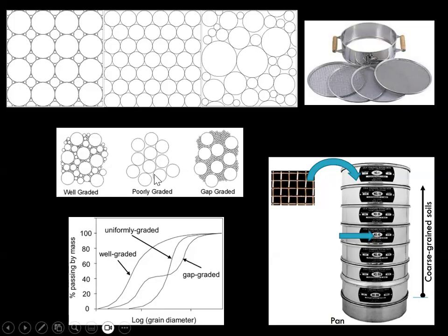But what do you think is the strong part and what is the weak part of the concrete? The aggregate, is that going to be the strong part or the weak part? Strong. And the Portland cement is going to be the weak part. So suppose you have a 50-story building and you're building taller and taller, like the Tower of Babylon or something. It starts to crack the bottom floor. It's going to crack along these cement lines. Or suppose there's an earthquake that shakes it all. It's going to crack along the cement lines.